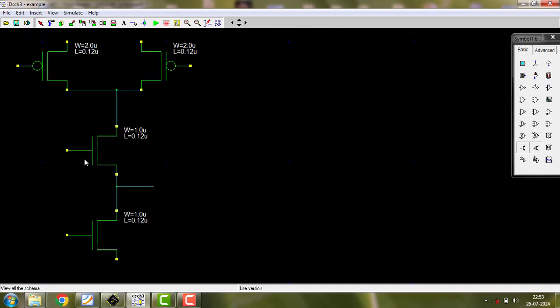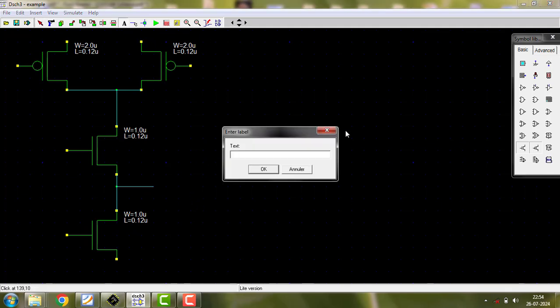So the impedance of NMOS is R by K, impedance of PMOS is 2R by K. Suppose you want to get equal rise and fall, these two are parallel, so any one resistance will be considered. So 2R by K must equal R. Just read it. 2R by K equals R since it is parallel.